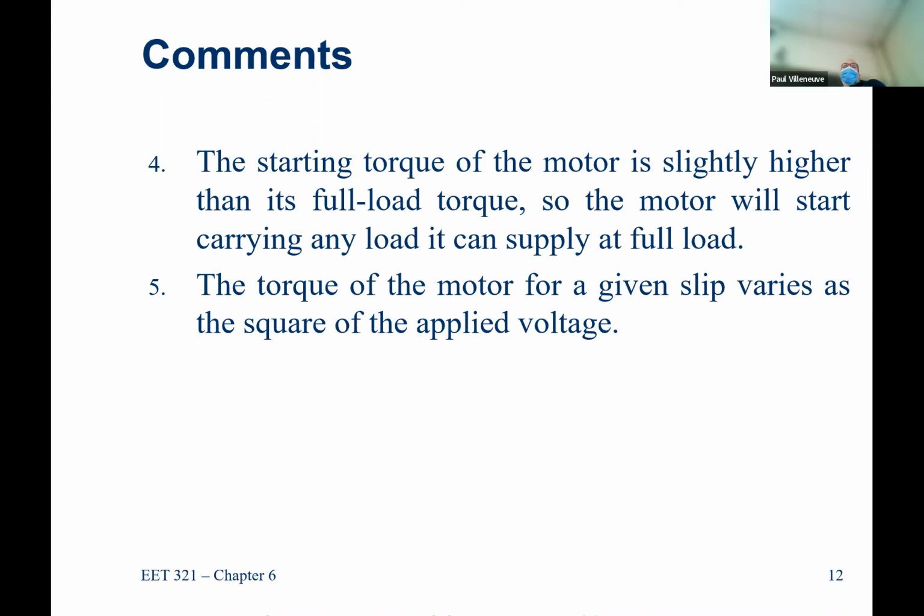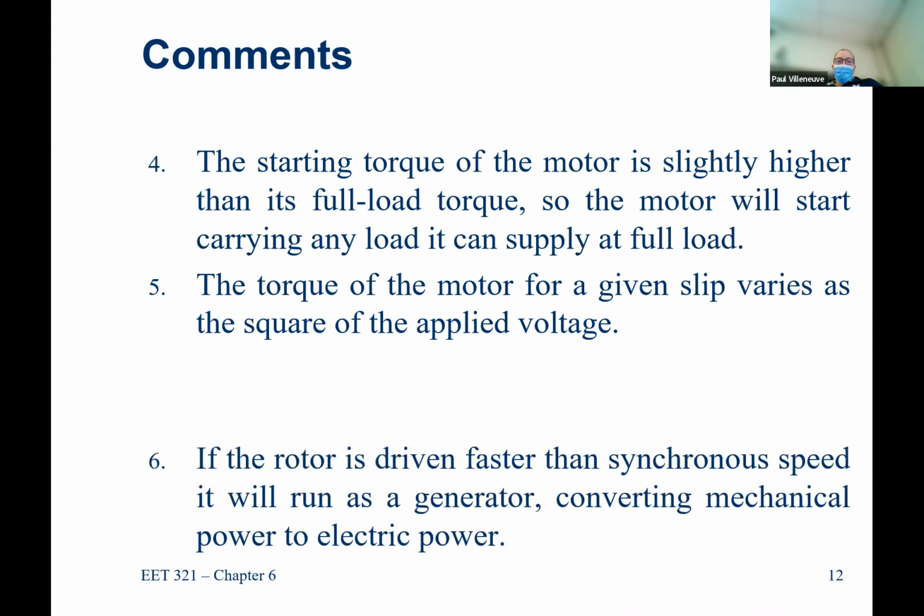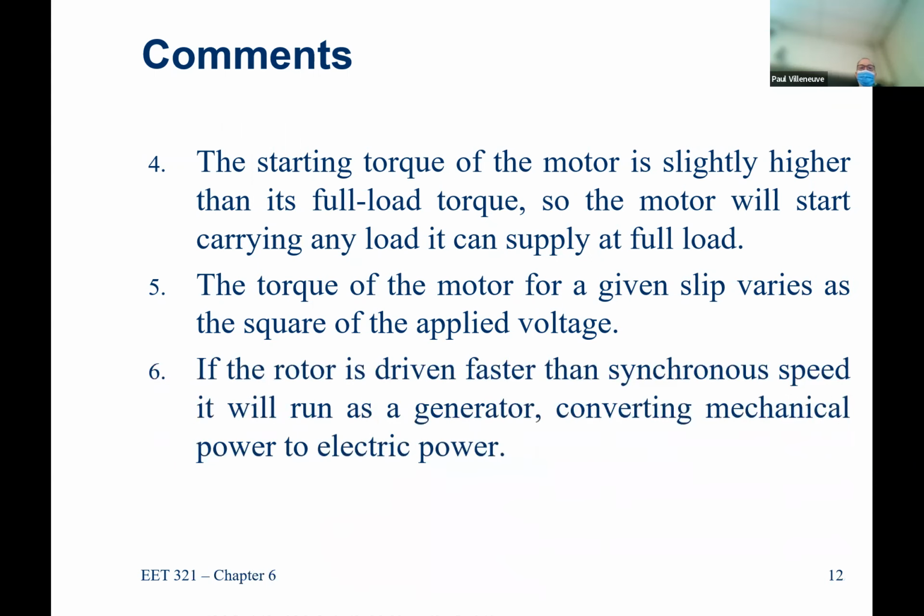It's called a reduced voltage start motor. They used to be very common and very inexpensive, but you literally drop the applied voltage and it takes less torque, which means it takes less current. So it takes longer for it to start up, but you don't need as much capability to start it. But voltage is the biggest change.